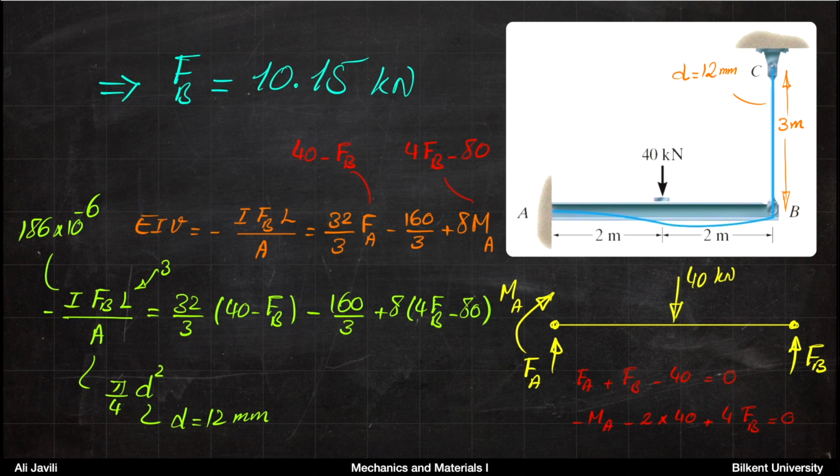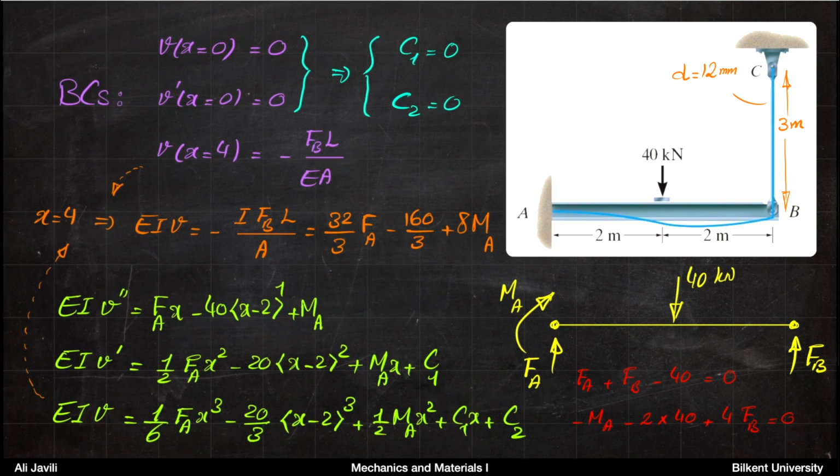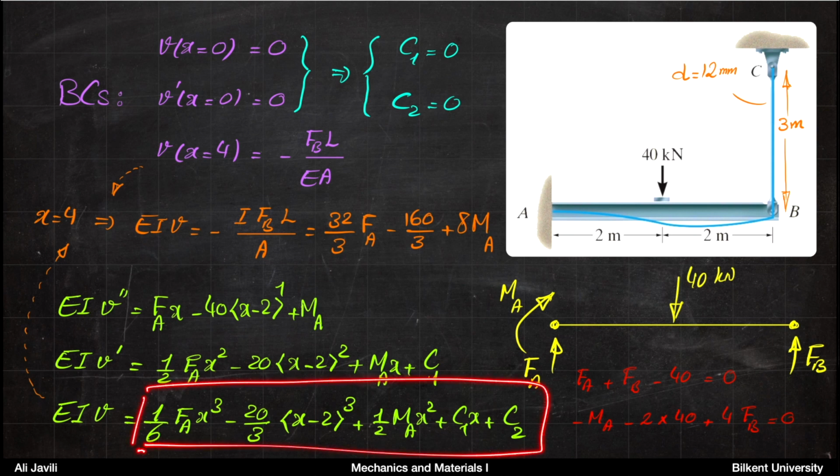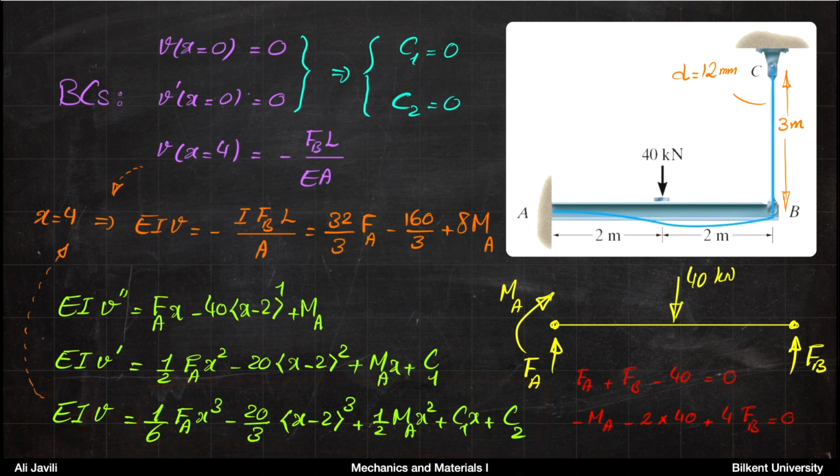Okay, so this is how you need to solve this. Again, if I just go 2 or 3 slides back, this is really the crucial step here. All you want to do is to calculate V from this equation. Pay attention that you need to divide it by EI. You calculate V from that equation, and then you insert that. This is EIV, that's why we have an I here.